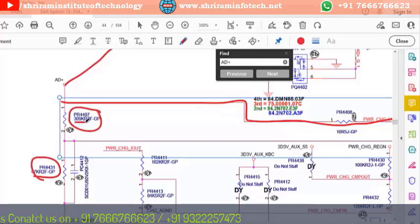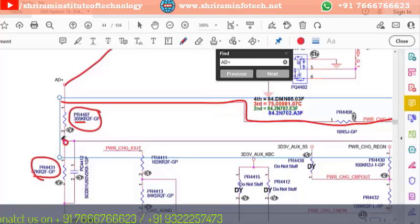So you can use the multimeter and check the value of this resistor. The resistor value is 309 kilo ohms, and this other resistor value is 47 kilo ohms. So according to Ohm's law, the voltage will drop to somewhere around 3 volts, somewhere around 2.7, 2.8, around 3 volts. So you have to check that.